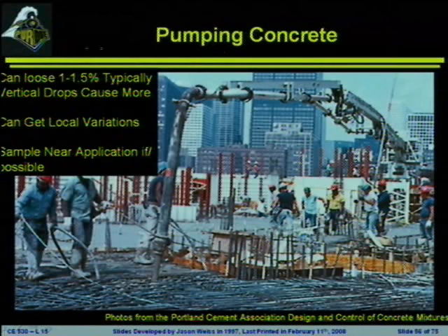One of the things I will point out is that it's typical to lose 1 or 1.5% on pumping. A lot of times you'll notice that steep vertical slopes or vertical drops will cause a big issue. Essentially, if the concrete is going to be dropping a long distance, now what we've seen here is not a very long distance on this picture, but if you see the concrete being pushed straight up and then dropping straight down, you wouldn't be surprised to find out that it's going to squeeze out the air when it lands, or it's going to squeeze out the air because we're basically putting it under a hydraulic pressure to be pushing it through this piping system.